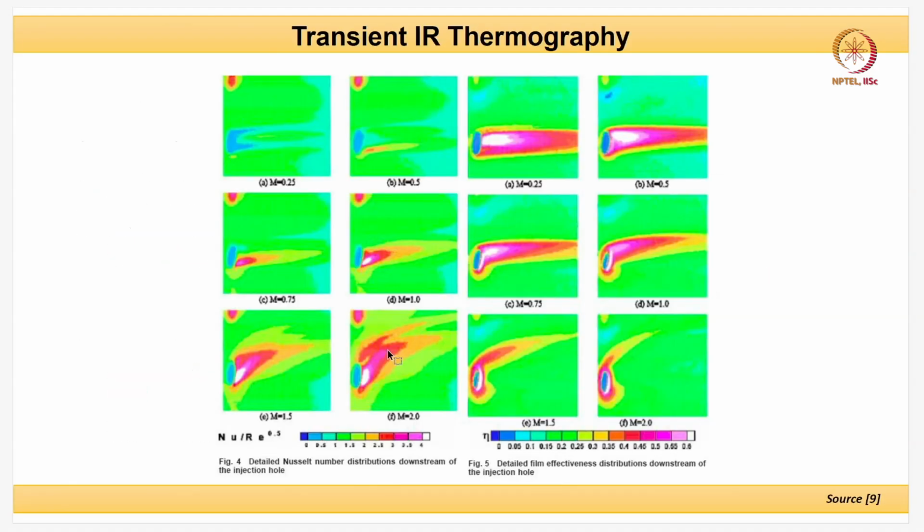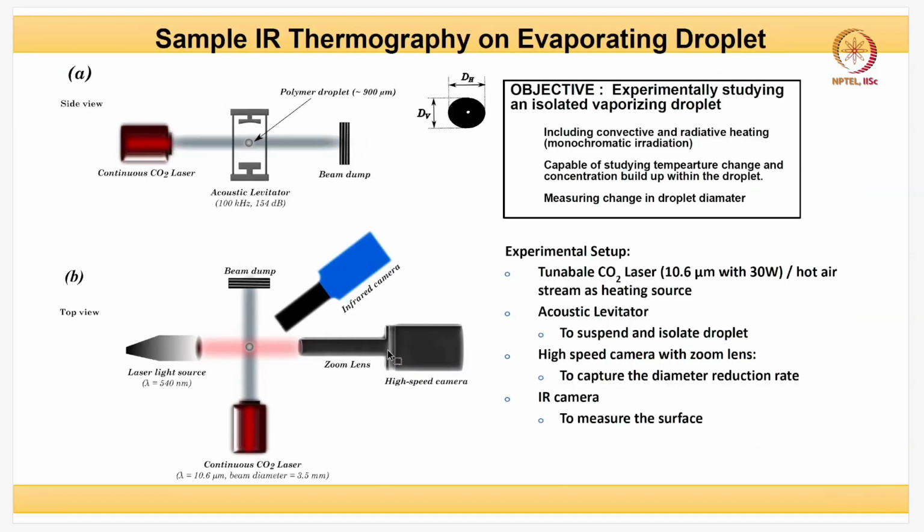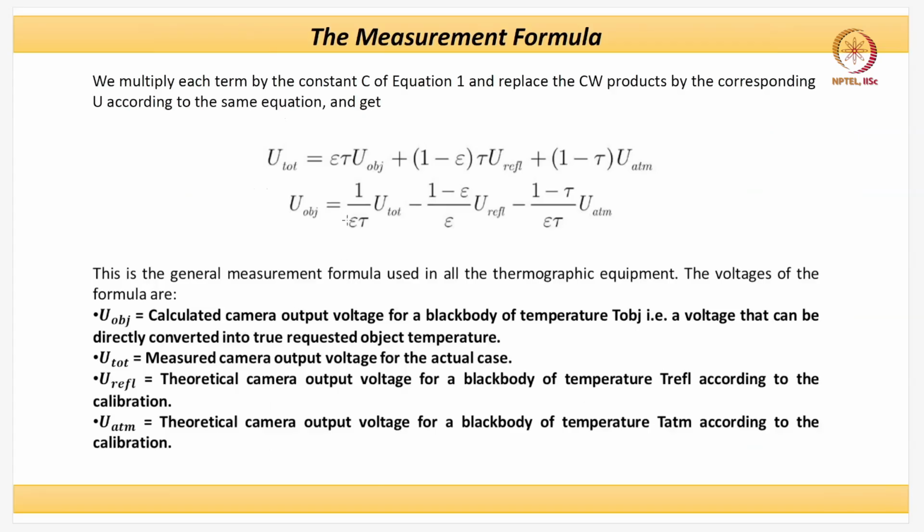But there are certain things that we wanted to mention at this particular point. We have come to the close of the lecture, that IR thermography is based on a certain amount of calibration and details that you get from the camera signal and how you calibrate it. You also have to key in, this is what I forgot to mention, epsilon and tau. These are parameters that you need to put in. The atmosphere is normally pre-calibrated, so these things are already there unless you want to work in a different atmosphere, but normal atmosphere conditions are given. Epsilon is something that you have to enter.